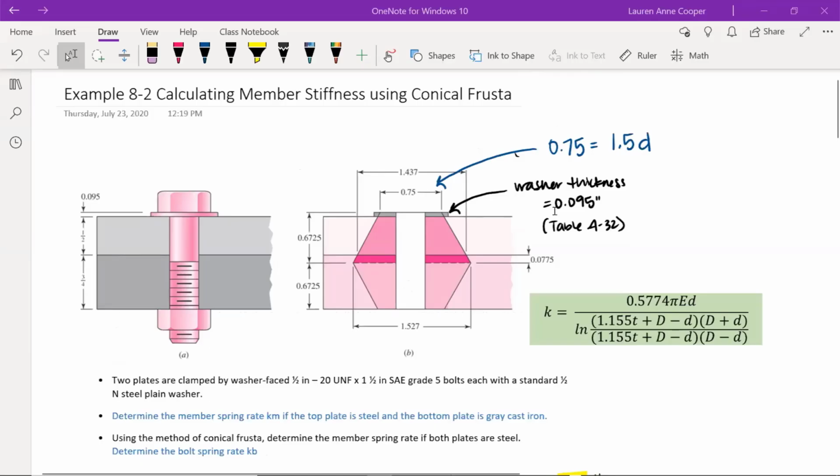So here we go. I will step through this problem and also show you my analysis tool. I just have the problem statement repeated here, as well as equation 8-20 for reference. So we are going to find the K value for three different frusta, 1, 2, and 3. Some preliminary things before we get started. You'll see that the geometry has been provided for you in this first example, but that won't always be the case. But this is a nice first example to step through because you don't have to worry about getting the wrong geometry, and you can use this example to calibrate your tool pretty well.